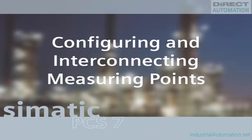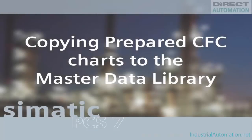In this sequence, we're going to show you how you can implement your own templates, that is, sample solutions for specific process automation functions, in SIMATIC PCS7 as a basis for carrying out the application engineering of your plant. In addition to these sample solutions, which are created in the form of CFC charts, a sequential control program in the form of an SFC chart is also used. The SIMATIC PCS7 library comes with standard templates, for example for motors, valves, and controllers. For the purposes of this exercise, we will make use of a customized library to show you how you can use your own company-specific templates.